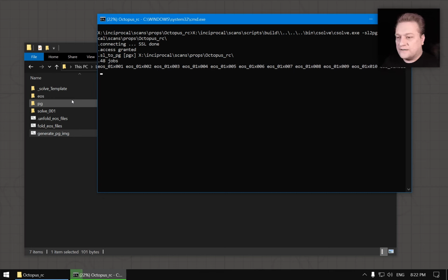But for a basic version of a reality capture pipeline overview, we'll be using just the same image set for both alignment and geometry reconstruction. In this case, for geometry, it's enough. 3 loops is good enough. And the reason we do 3 loops is that we want those cameras to form 3 perpendicular planes. They don't have to be perfectly perpendicular, but that would be equivalent of having cameras observing the prop from basically